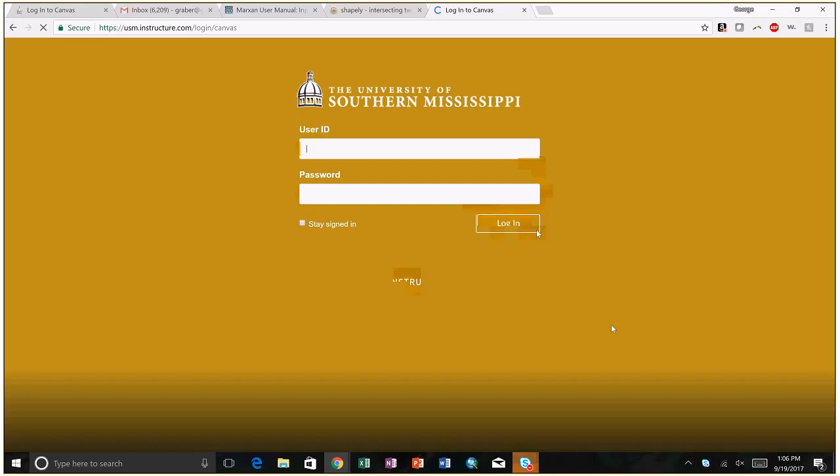All right, so this is the summary. You've got the 3 segments: the space-based positioning system with satellite, control, and user segments. The carrier phase is the accurate one, versus the code phase. Positioning, range measurements. The key to this is range measurements, distances. You've heard the term triangulate your position. This is actually trilaterating your position, or using 3 different distances to get to a position.